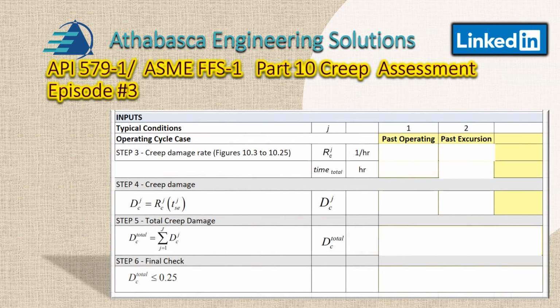Step 3, creep damage rate. From the previous slide, we learned that the degradation creep damage rate is shown there, and the past excursion rate is shown there from the damage chart. We had accumulated damage of 175,000 hours. So that tells us, from our earlier discussions, that we're approaching the end of the service life of the equipment anyways, and we have a past excursion, that was the period.